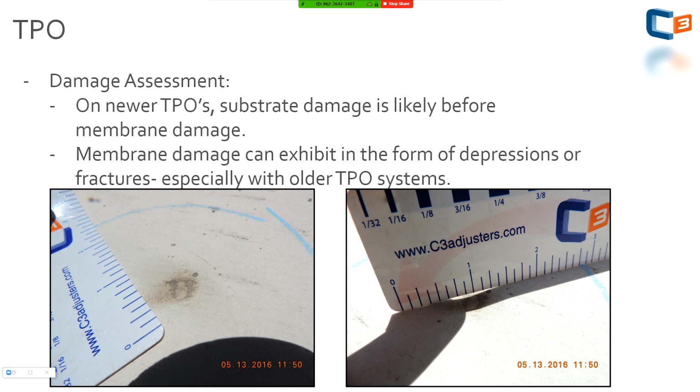So in this photo, we actually see, again, that dirt gather in those dimples. It's a very bright roof. It's hard to see. But in our test area, we notice these. And then a lot of times to document this, we'll put a straight edge or a ruler over that area, and we can see that depression. We're quantifying the extent of that depression.